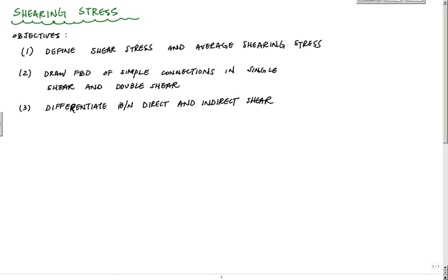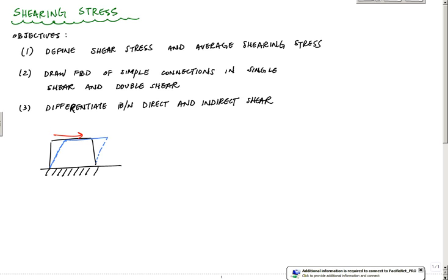But here, just to get started off, in terms of shear stress, whenever I think of shear stress, I think of something sliding by something else. So the image I have in my head is a book, right? If a book is resting on a table and it's attached to that table right here, and I put my hand on top of the book and I push alongside of it, I know that this thing will deform like this right here. It'll essentially shear right here. And if all the pages were bonded together, I would have shear stress develop in between each layer within the material, or within the book between the pages. And that would be kind of like shear stress, right?